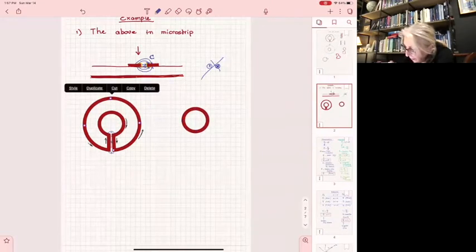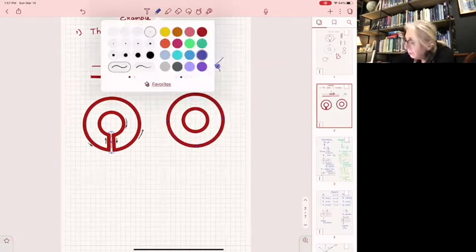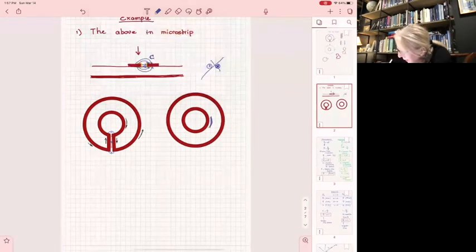And then I would put the external conductor if I want it. But then there are two things that I would like to do. I would like to change the direction of the current, because if the currents have opposite directions in between the small loop and the upper loop, then they cancel part of the field. So I would like to change that, and so I would like to get rid of that capacitance. So what I want to do in this one is have the same direction of this current here, and I'm going to have the same direction there.